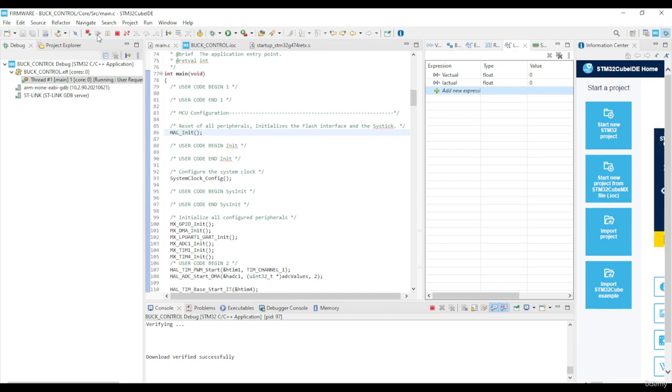There, resume. So I have a converter here, of course, with the duty cycle of, in this case, 400 divided by 849, which is 47%. It's almost 50% duty cycle. So I'm actually going to turn it on, and you're going to see the live readings show up. And there you go, you have the live readings. It's fluctuating quite a bit.